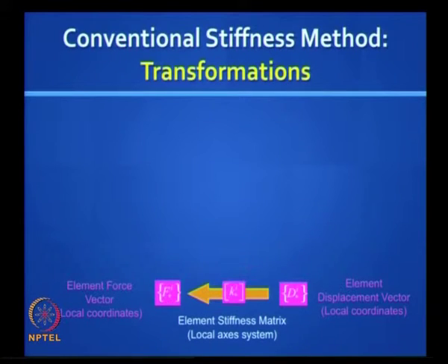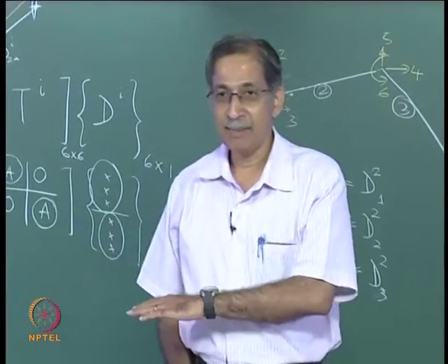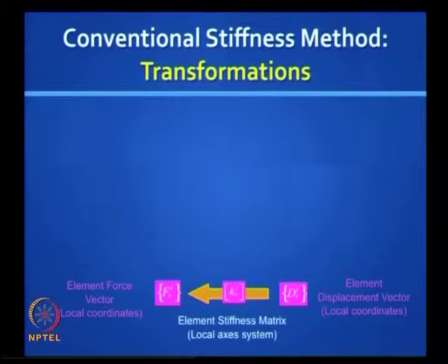Okay. So let us take this one picture, it is a beautiful way to understand it, I want you to draw it. I am going to draw a playground with 4 corners. At the bottom line you see how I have done it, it is very easy to do. I am putting the forces on the left side, the displacement on the right side, right. So the first transformation that I have is the element displacement vector in the local coordinates with the star. If I have this and if I pre-multiply it with the element stiffness matrix, I get the element force vector in the local coordinate. Is this clear?